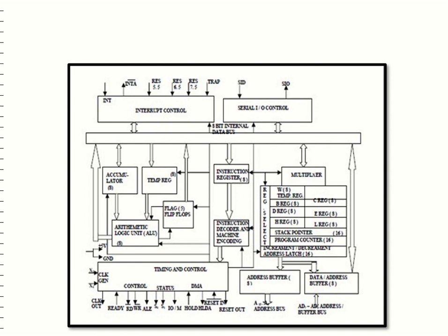Timing and control unit. It provides timing and control signals to the microprocessor to perform operations. Following are the timing and control signals which control external and internal circuits. Control signals, for example, ready, read, write, etc. Status signals, S0, S1, input, output, etc. DMA signals such as hold, HLDA, and reset signals are present.